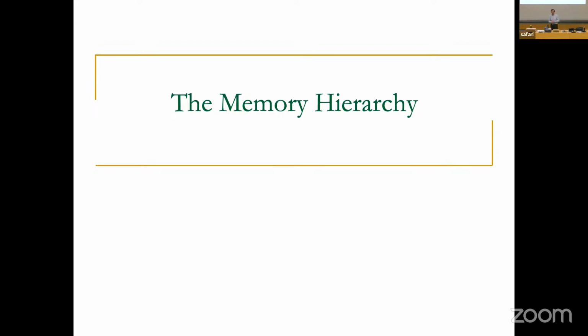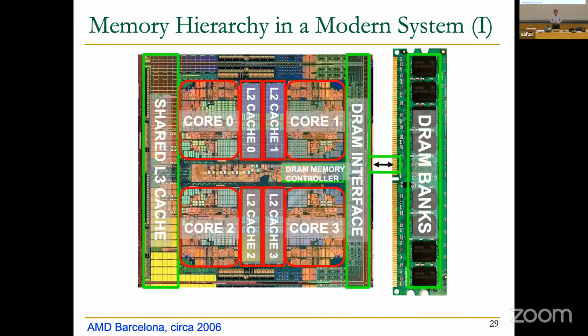In addition to enabling much better systems, the disparity between these memory technologies and also requirements we have from the memory system require us to have memory hierarchies. And if you look at the memory hierarchy, different parts of it have different technologies. And it can have even more technologies. For example, some of the non-volatile memories can be on chip and replacing SRAM technology because it may be a good fit over there. And people have been proposing it. It has not happened yet, but it may happen soon.